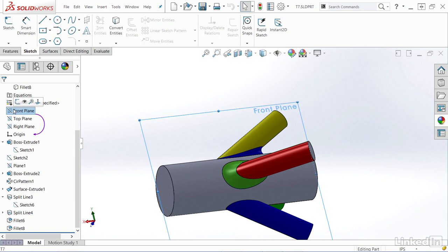It's not actually going all the way up to the top of that surface because we have it set up as a circular profile. If instead I change it over to curvature continuous, notice it does go all the way up to both of those lines, and that's exactly what I want. So you have a lot of options you can play with here. You can change how you're cutting these surfaces, what you are doing to define these radiuses and things like that, but you really have a lot of control with this, and you can really define exactly the starting point and the ending point for that fillet.